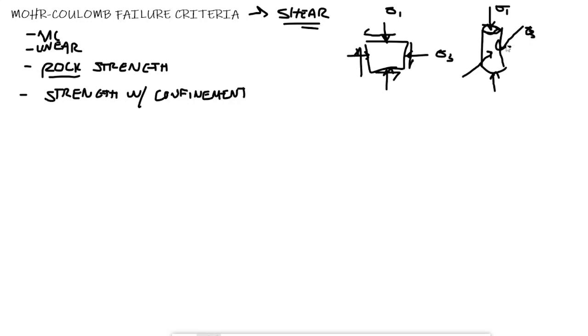And this isn't just applied in one plane. You'll have it around the entire circumference of the cylinder. I'll just draw it like that to simplify it. But this in a TCS cell would usually be from a sleeve that will contain an oil or some fluid that you can increase the hydraulic pressure of to apply, again, that confinement around it. So, of course, to detail, whoa, we can do better than that line right here.